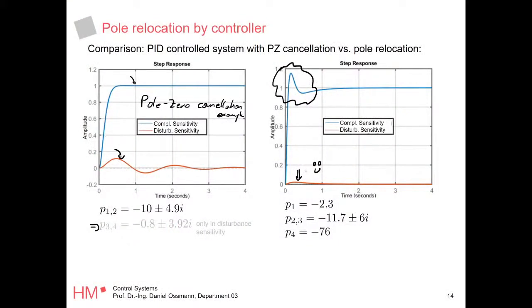On the left, the disturbance excites our system and we get a lot of oscillation, while when the pilot is inputting something, the blue line, it looks pretty nice. Here, the disturbance is nearly fully mitigated. We don't have much effect of the disturbance in our loop. However, when the pilot commands something, he gets a lot of overshoot.